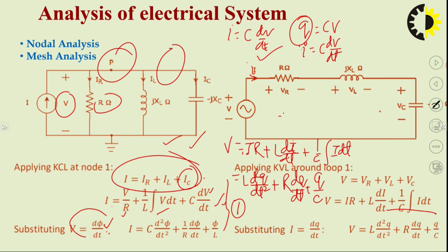So, we have seen that when the components are connected in parallel and series, we get these two equations. We will use these equations to get the electrical equivalent of a mechanical system, because we want to draw an electrical system from a given mechanical system. Why do we want to draw this? Because the mechanical elements are costlier as compared to these components connected in a circuit.